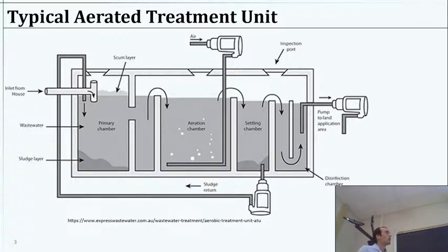Okay, another possible arrangement. I think this was a company in Australia. They have systems like this where we see the influent coming from the house here on the left, and we can see they're showing a sludge layer forming. Wastewater comes in here, you'll have some scum on the top. Then essentially it gives some sedimentation here for the large or quickly settling stuff flowing through this